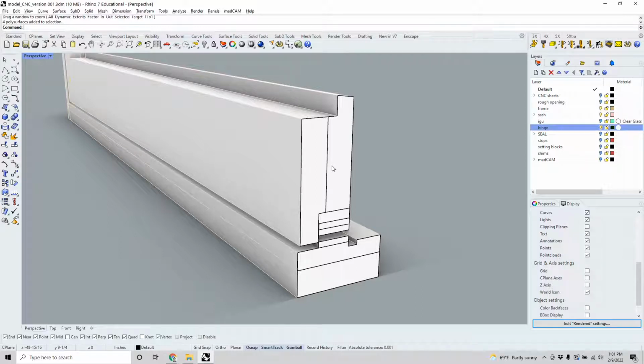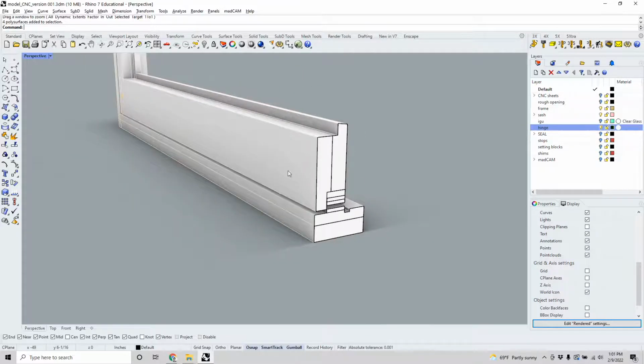But I think if you open it in, you can also clean the window glass on the outside much more easily. And for installation purposes, if you open the hinge in, that means you can hold the entire sash more carefully, more sturdily, as you install them in the rough opening. Whereas if they open out, you either have to fit it onto the whole frame and install the frame, or if you install the sash later, you have to dangle this thing out of the window, which is a little precarious.